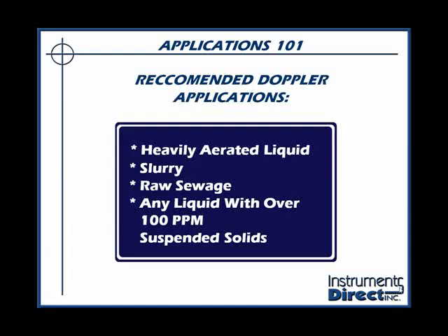So what we've learned is an ultrasonic Doppler flow meter must have suspended solids or aeration in a process liquid for it to work. Generically speaking, it differs between the brands, but most brands require that liquids have at least 100 parts per million of suspended solids, not dissolved solids, suspended solids that are about 75 to 100 microns in size. No suspended solids or aeration, you'll get no signal.